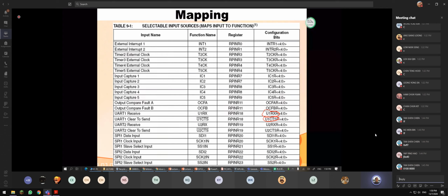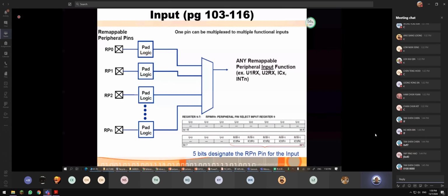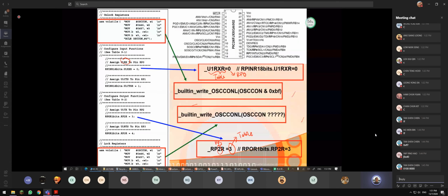But it's very important when you design your PIC24 for the final assignment. You probably need a lot of pin remapping. One of the reasons I didn't ask you to use external interrupt is that if you want to use a lot of external interrupts, you need to do a lot of pin remapping, and moreover, I hadn't taught you remapping pin. Now I have taught you remapping pin, maybe you can use an external interrupt if you want, but I still don't recommend it. So it's up to you.